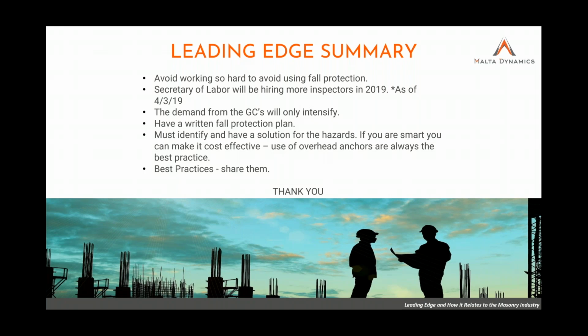You must identify and have a solution for the hazards that you're working with, and if you're smart, you can make it cost effective. Using an overhead anchor is always the best practice, and it doesn't have to cost a lot of money. I think a cross-arm strap is probably one of the best, most universal solutions, and that's a $25 anchor. It doesn't get any more cost effective than that.